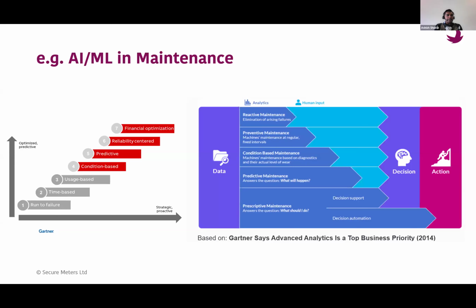But to get the condition, of course, you have to have parameter monitoring so that you can decide whether the oil has really deteriorated and whether you have to change your oil or not. That is condition based. Predictive means now you know the condition of your vehicle, or of your assets if it is in the electrical network. If I'm able to predict how long I can run with that condition, then it's predictive maintenance. So I know I'm driving my car more than 10,000 kilometers.